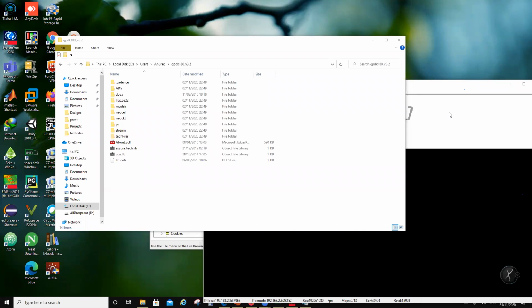Method of moment means that you are treating everything as a thin sheet, and all the meshing is done in sheets. The Z currents are basically mathematical fudging. So they call it 2.5D, but it is not really 2.5D. It is 2D with some add-on. Next thing is 3D simulators. Method of moment is not a 3D simulator. Anything based on method of moment is not a 3D simulator.